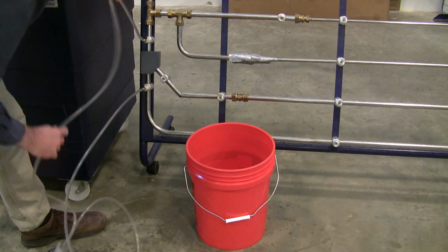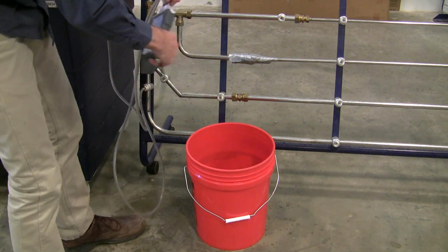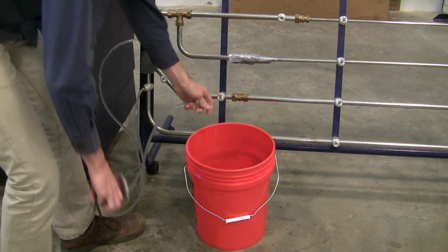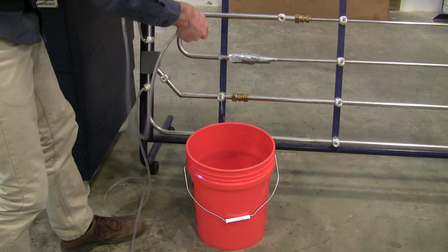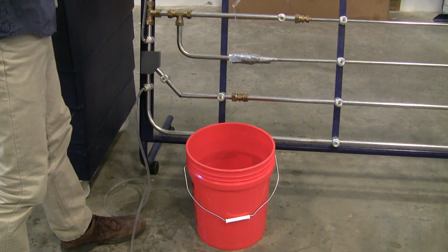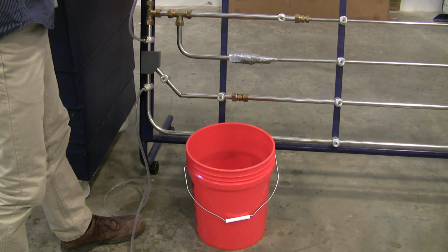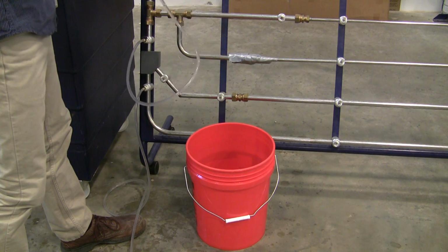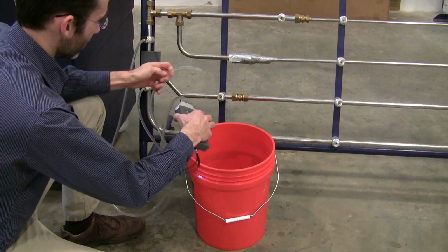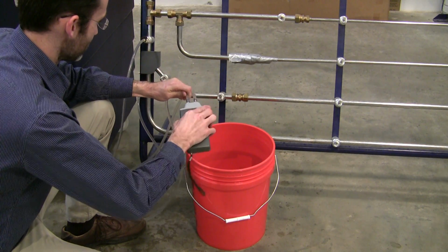And I see that there are air bubbles in the line, and so I'm going to purge these lines of air. All you have to do is disconnect it from the pressure meter, and water will flow into the bucket. I'm going to raise it up to try and coax those air bubbles out of the tube. I can see there's actually a pretty long stretch of air in there. This will really improve our accuracy considerably to make sure that there's nothing but liquid in there. And I can just plug it back in and it's good.